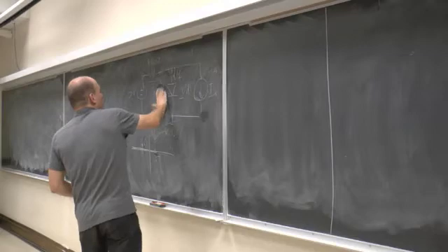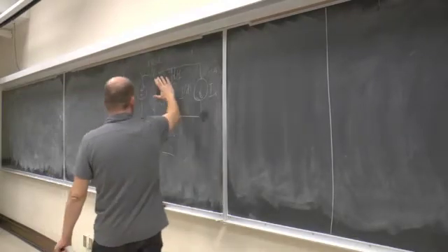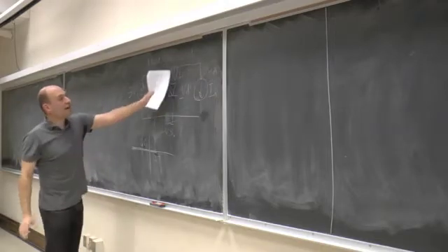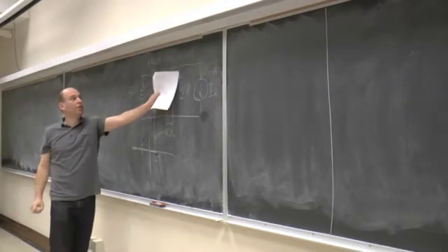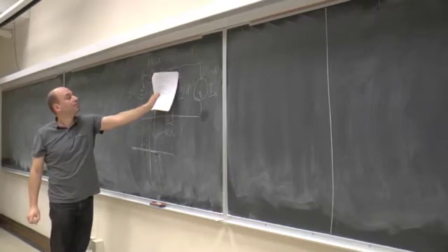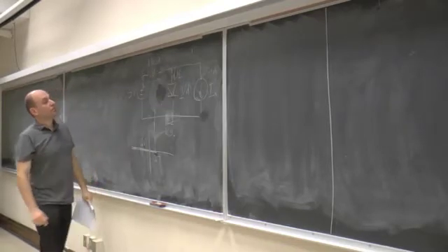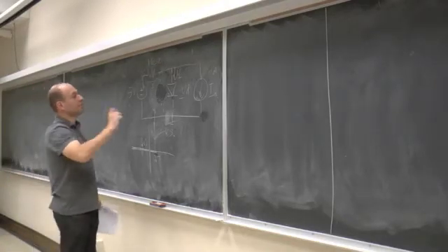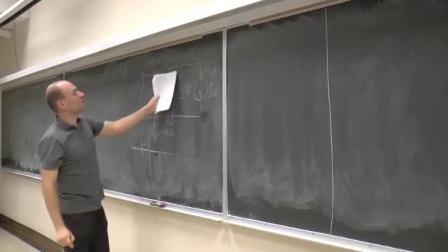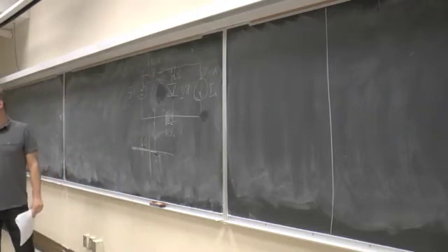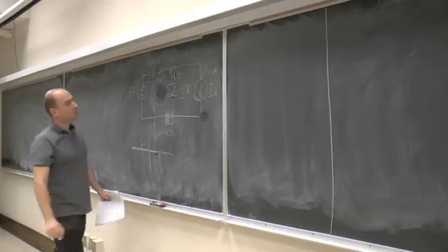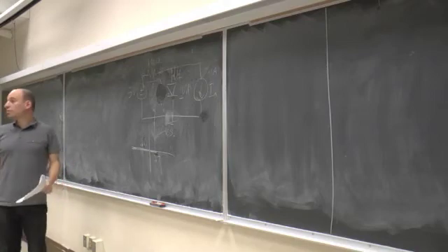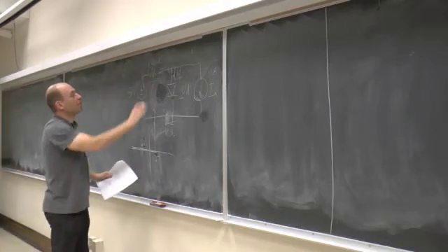But right now, let's just assume it's an open circuit. So you do a visualization or use your hand, okay? Open circuit, then this is 7 milliamps. If this diode is an open circuit, what is going to be the voltage drop across the resistor? The voltage drop across the resistor is going to be 7 volts, right? 7 milliamps times 1 kilo ohm, 7 volts. That's going to be the voltage drop, okay?